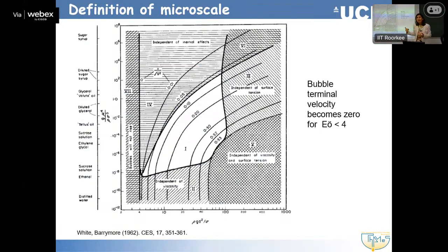We will talk about plug flow, Taylor flow in subsequent lectures. If people have worked with two-phase plug flows, Taylor flows, they will know that you can have a very nice, well-defined Taylor flow in channels up to quite a large diameter, a few millimeters. What you start seeing from some point onwards is that some gravity is obvious.